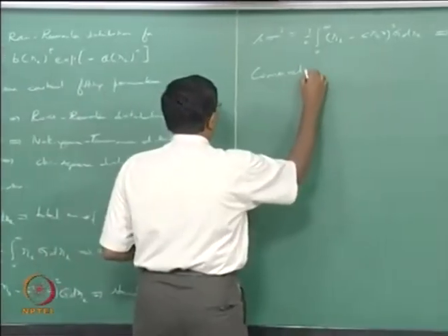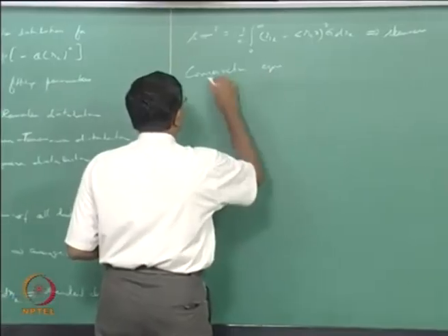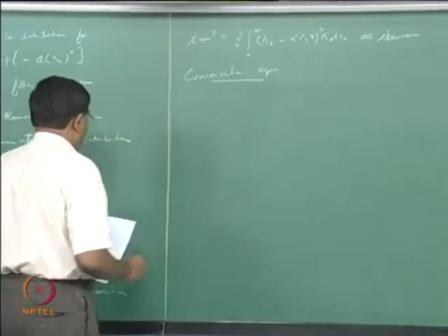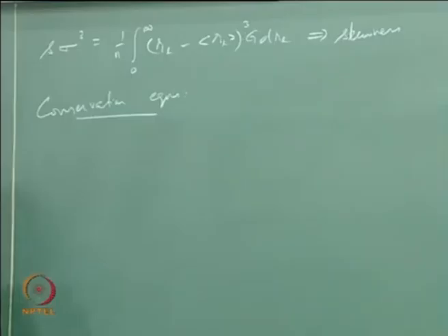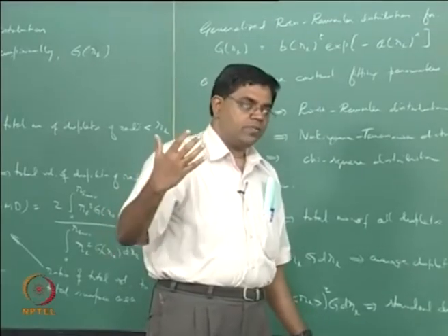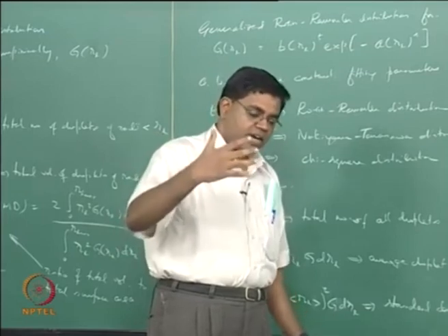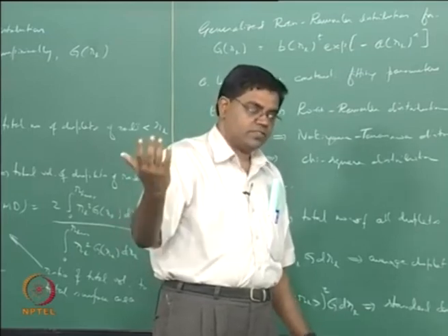So, conservation equations. Here we want to define rho f as the mass of the gaseous mixture per unit volume of the two-phase mixture. So you now have a two-phase mixture with droplets and gas, and the gas in turn is a mixture of gases.